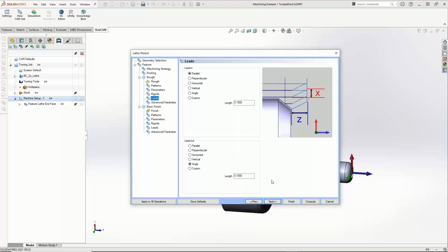And that'll be the same rule you follow with your 2-axis, your 3-axis mill, and even the lathe, anything you do. We put these values in here for a reason. They're the most common values that we run across, and they work. So unless you see a problem occur because of one of these settings, you're probably not going to change it. Or I'm not going to change it. And we won't know if there's a problem until we compute the toolpath. And even then, you might not know it until you simulate.